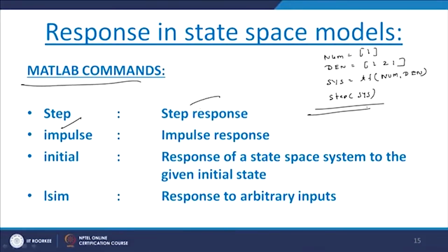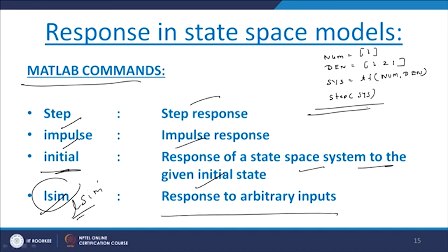So if you see the MATLAB literature, various commands are available which can help us get the response of a system. These are the commands: step is the step response, impulse is the impulse response, then there is the initial command, that is the response of a state space system to a given initial state, and lsim, this command is called lsim, for response to any arbitrary inputs.